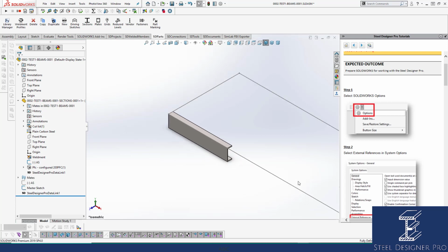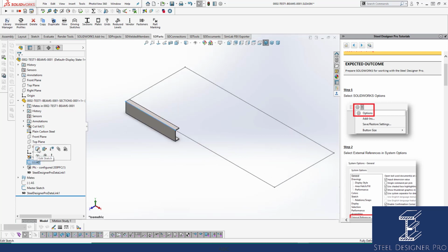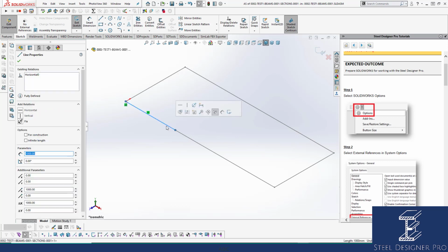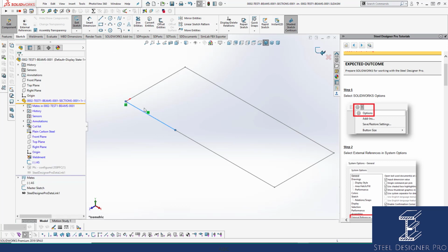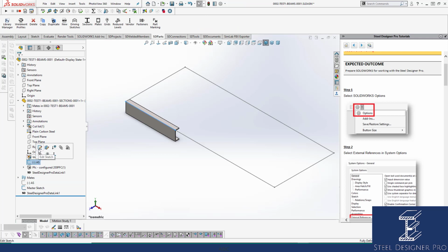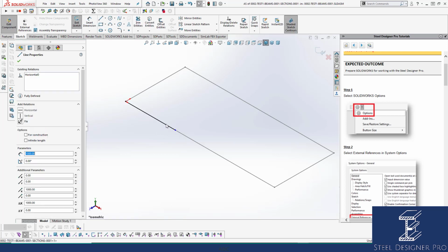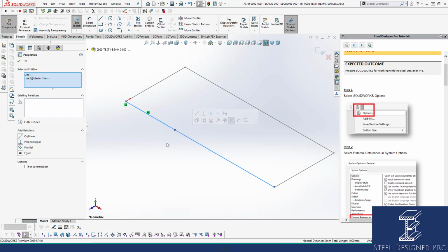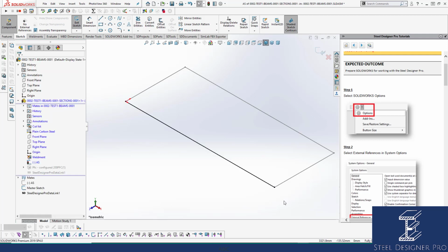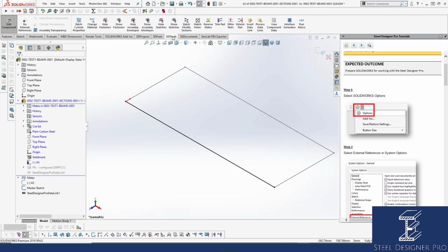Now we need to make it so that it stretches the length of the sketch segment. We select the sketch. Actually, I'll go back to what I did. I selected the sketch, edited the sketch segment, selected the sketch segment that's in the active sketch that we're working on, and now I've selected the driving sketch that's in the welded member, or the master sketch in the welded member, and now I'm going to make them have an equal relationship. Okay, now you'll find that having an equal relationship will allow us to turn this around if we need to via our tools, reverse mates.